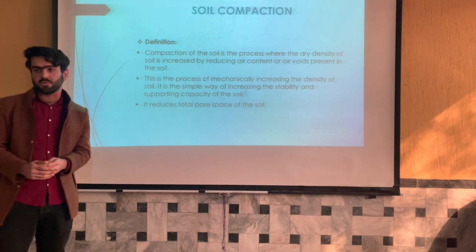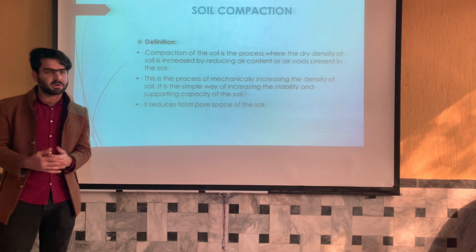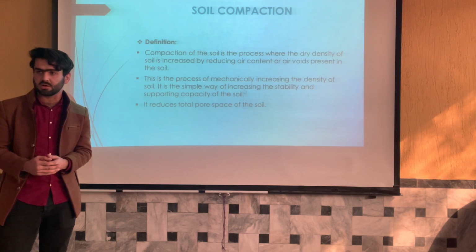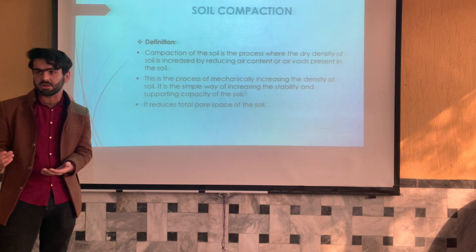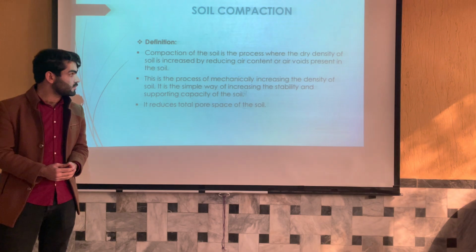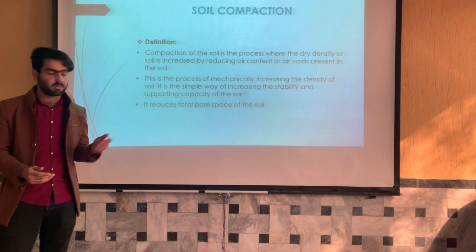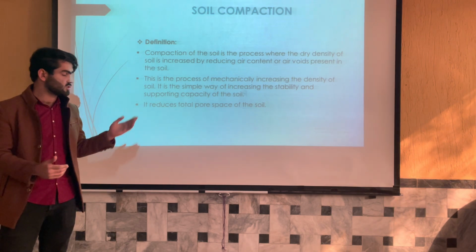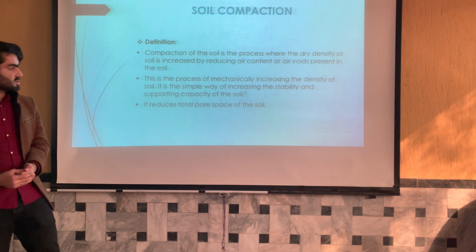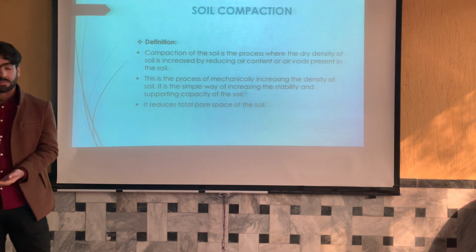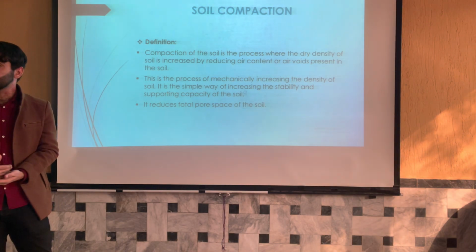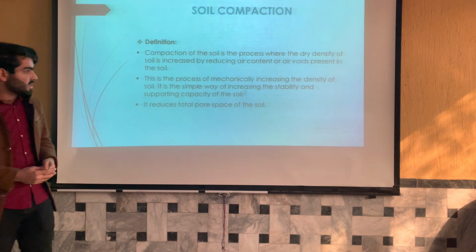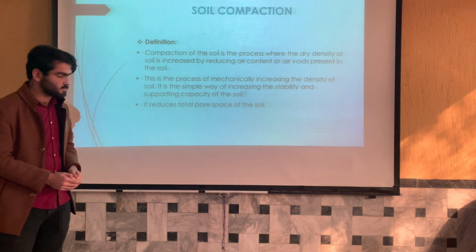By this we mean that when we apply pressure on the ground, we actually remove the air content from the soil, and by this the density as well as the shear strength, permeability, and other properties of the soil change. This makes the soil more durable and more able to support more loads. This is the process of mechanically increasing the density of soil.